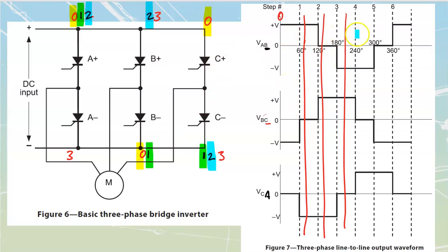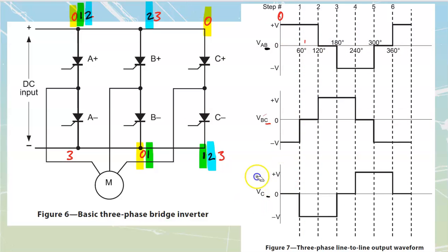And as a result, we get this approximation of a sine wave. You should be able to identify this as being a sine wave, and by the time that I would filter it, you would see that we have a sine wave that looks like that, another sine wave that looks like this, and another sine wave that looks like this. And we should see that they're all peaking at different times, 120 degrees apart inside of here.